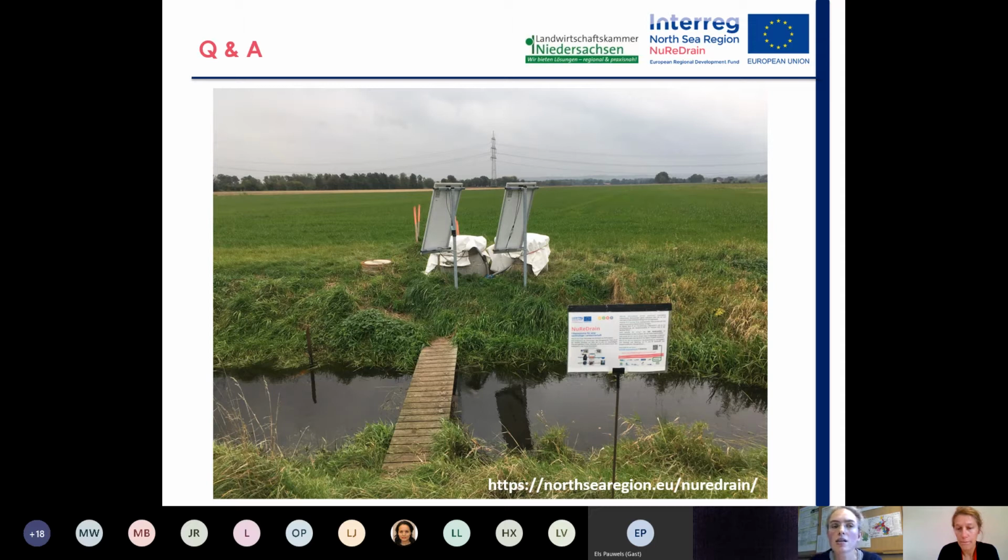But if I could wish for something, it would be a larger gradient. If we use even coarser material, then water is passed through the filter so quickly that there is a very low retention time. It's a very site-specific decision how coarse or how fine the material can be. The coarser, the higher is the hydraulic conductivity, but the lower is the contact time. So you have to figure out what the site-specific conditions are and what is the most important thing, and then follow one by one.